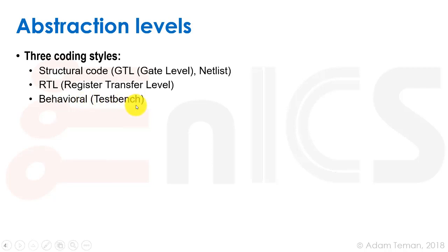We use this for writing test benches. A lot of times nowadays we don't actually use Verilog for writing test benches, but rather other higher level languages such as System Verilog, E, or others. But the Verilog hardware language, which was actually written for the purpose of writing simulations, has support for higher level constructs or behavioral code, and we'll see how to write test benches with it.